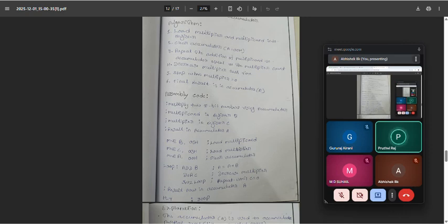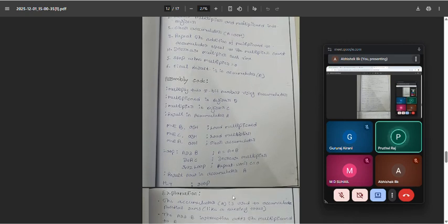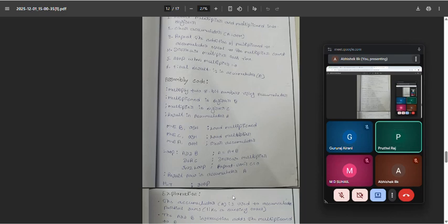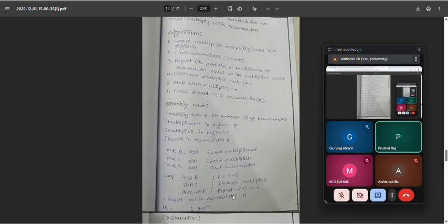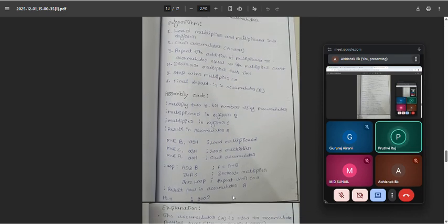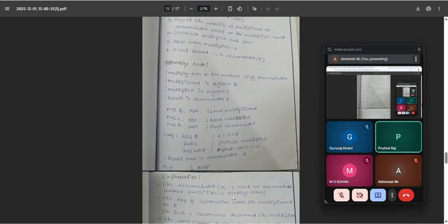The accumulator is used to accumulate the partial sums, like a running total. The ADD B instruction adds the multiplicand to A, the DCR C instruction decrements the multiplier, and JNZ repeats the addition until the multiplier is equal to 0. Next will be the sequence diagram, showing how the start and the stop will happen.